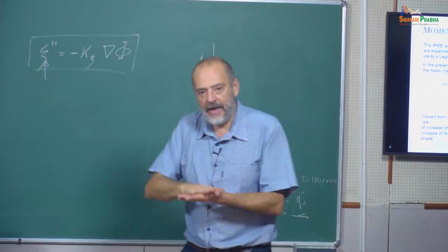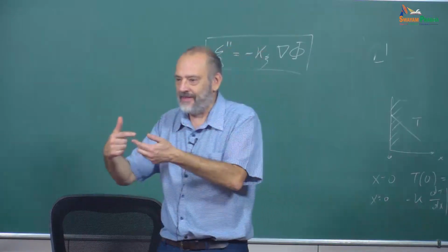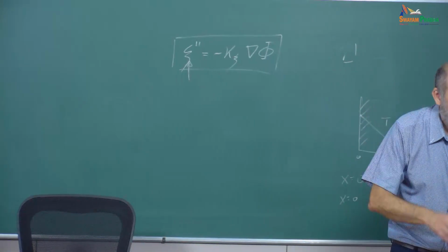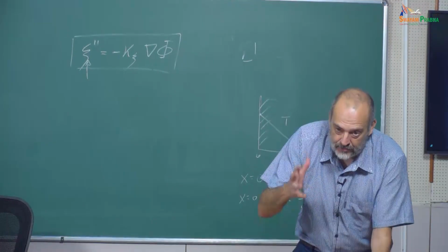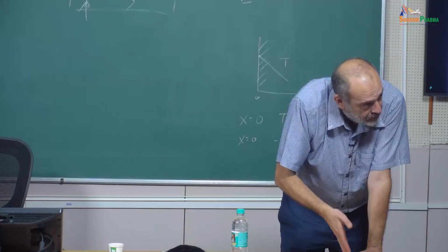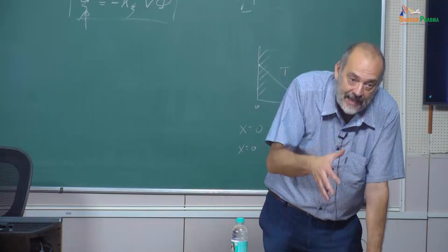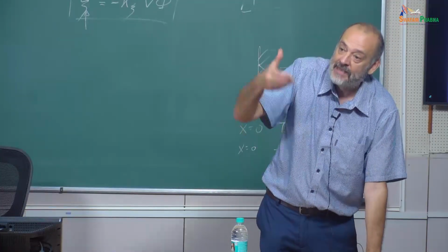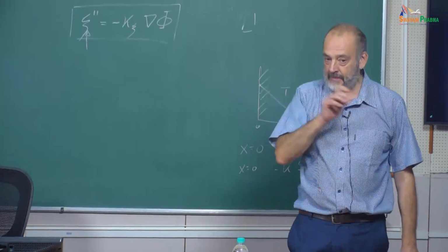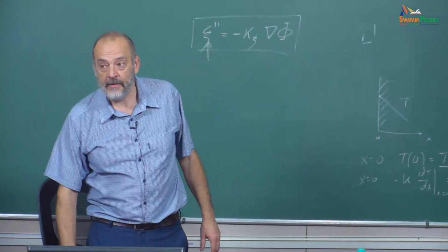So when you have a phase change, we are going to have mass that is maybe going in one direction or the other, and it can also be condensation. So you are producing a droplet because you have a condensing vapor. This means that the mass of vapor is going to the droplet, so there is a movement. We need to consider the momentum that is created by the fact that part of the mass from the vapor is going to the droplet. This was not considered before. It was a single phase. Is that okay?